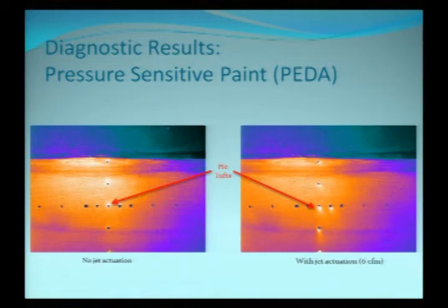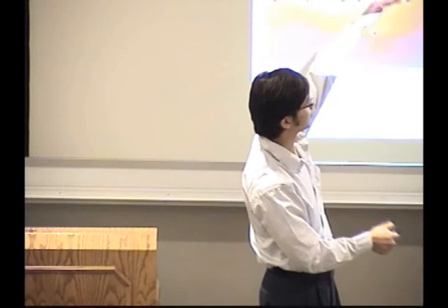After turning the pneumatic actuators on, you can see the helium tufts have started all blowing in the downstream direction, downwards, which means that the flow has managed to attach somewhere above this line, upstream of this line, and now it is flowing smoothly as it should, hugging the surface of the curve downstream.